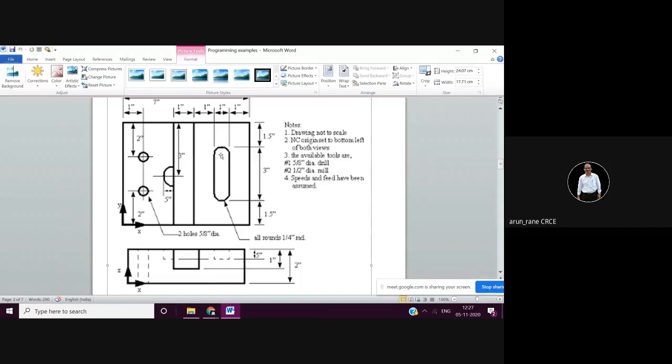Okay, you are going to get a small land here, but it is fine. At a student level, it is acceptable. Practically in the industry, it will not be accepted. But now you have a constraint because you have this radius as 1/4, so you cannot use more than half inch. If you want, you can write a note also. So two cutters, one is the 5 dia drill and another is the half inch dia milling cutter.